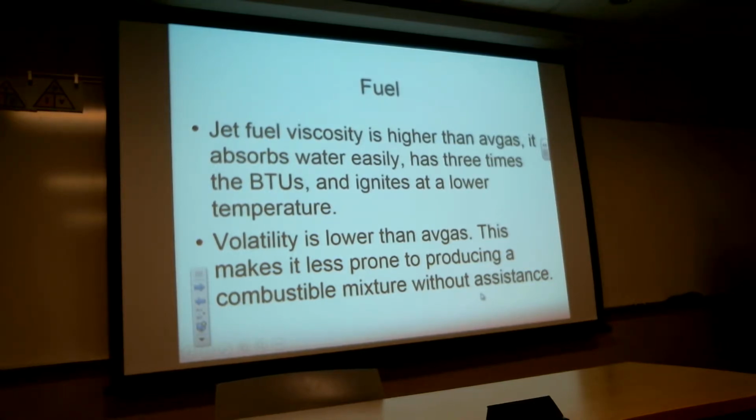Turbine engines run on gasoline, would you guess? Sure, they can. A lot of times there's a little adjustment you have to make. Sometimes the FADEC, if you're running a FADEC, will also sense the weight and density of the fuel and will compensate because of the different volatility of the fuels. Gasoline's going to burn a little bit hotter, a little bit leaner, so you're not going to be creating as much thrust pound per pound of fuel, but certainly it can run on gasoline.